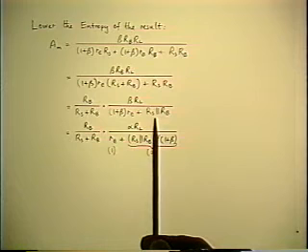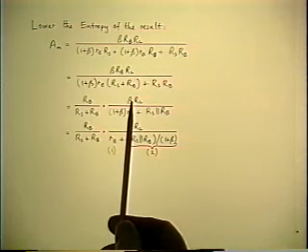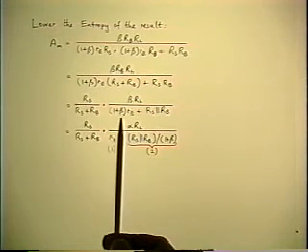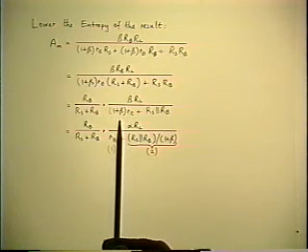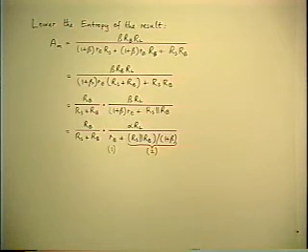One more thing we can notice about this result is we have a beta in the numerator and we have a 1 plus beta in the denominator. Now beta is a large number. At least it is in any transistor that you're not going to throw away. But it's also one of the most variable parameters. It's poorly controlled. In fact, it's a second order parameter of the device.